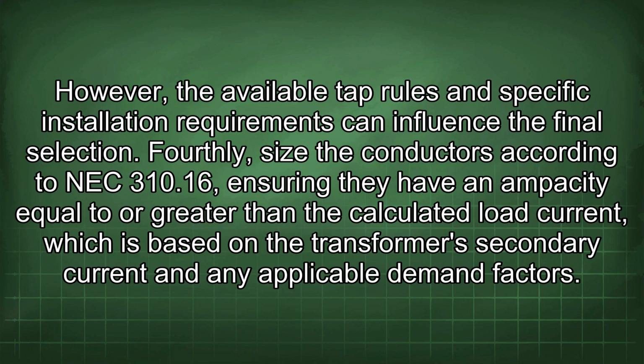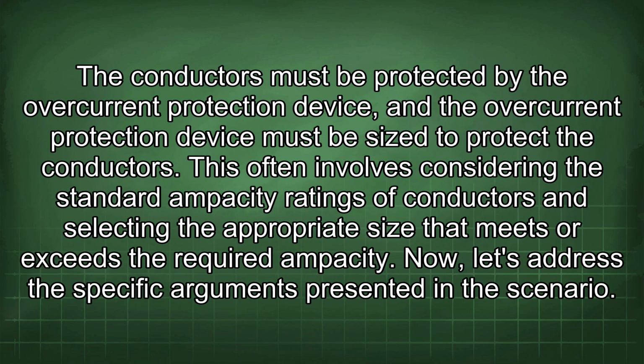Fourthly, size the conductors according to NEC 310.16, ensuring they have an ampacity equal to or greater than the calculated load current, which is based on the transformer's secondary current and any applicable demand factors. The conductors must be protected by the overcurrent protection device, and the overcurrent protection device must be sized to protect the conductors. This often involves considering the standard ampacity ratings of conductors and selecting the appropriate size that meets or exceeds the required ampacity. Now, let's address the specific arguments presented in the scenario.